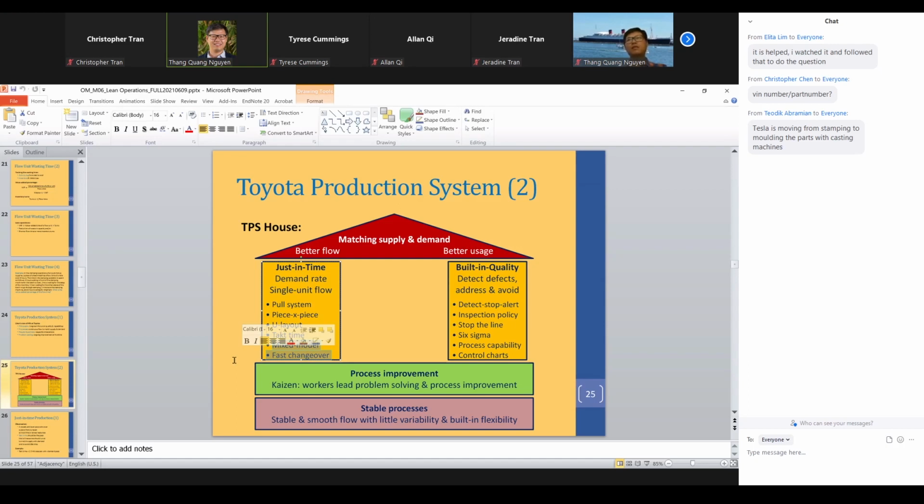So if we mix the different models on the same assembly line, then now we can even out the workload for the workers, right? Because the demands of different models are different. So we can even out the workload for the workers, for the tools and equipment, right? To improve the effectiveness of our resources. So that's the reason why they do mixed model.